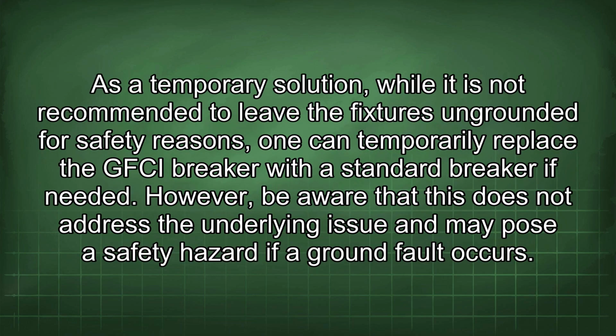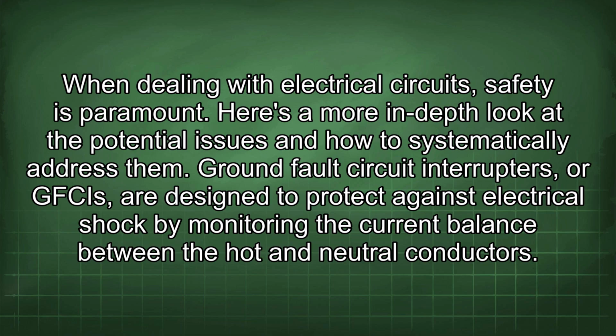As a temporary solution, while it is not recommended to leave the fixtures ungrounded for safety reasons, one can temporarily replace the GFCI breaker with a standard breaker if needed. However, be aware that this does not address the underlying issue and may pose a safety hazard if a ground fault occurs. When dealing with electrical circuits, safety is paramount. Here's a more in-depth look at the potential issues and how to systematically address them.